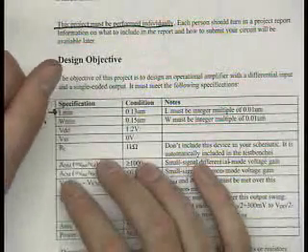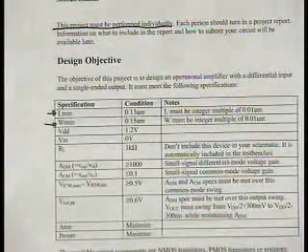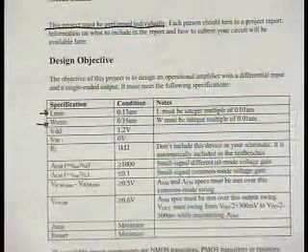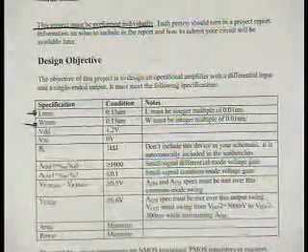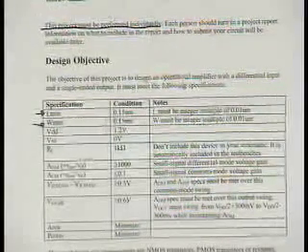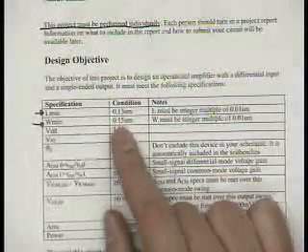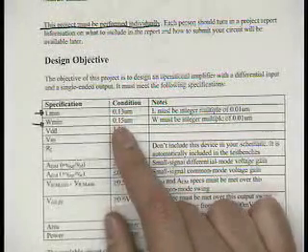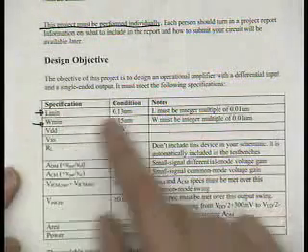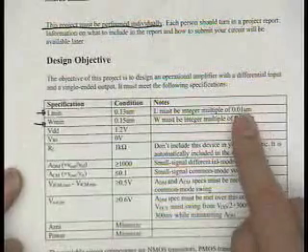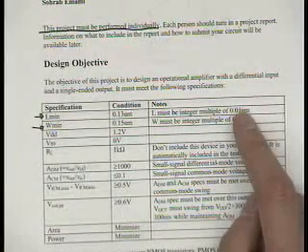So let's look at the specifications here. So first off, there's an L min and a W min. And what that basically means is you're designing your transistors. You get to size your transistors. You get to pick the sizes. This is a 0.13 micron process, and this process has certain design rules. Devices cannot be fabricated that have a length of less than 0.13 microns and a width of less than 0.15 microns. Okay? Pretty straightforward. The other constraint is that all your lengths and widths must be integer multiples of 0.01 microns. And that's simply because in real processes that's what you'd have to do.